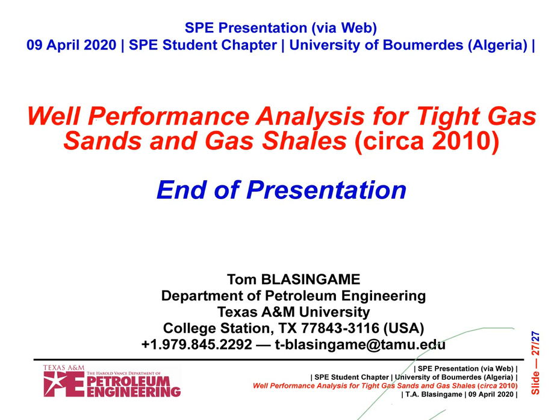Now, the way that would work is you would have to somehow have a robust data set. You'd have to know how much water you pumped, how much sand you pumped, how many fracture stages you have, how many clusters per stage, maybe even how many perforations. You'd have to know something about the reservoir. You probably wouldn't want to compare parts of the reservoir that are not geologically consistent. But once you start with that, then you go back and you have that information, and you can compare these production profiles, and then you can take those comparisons.